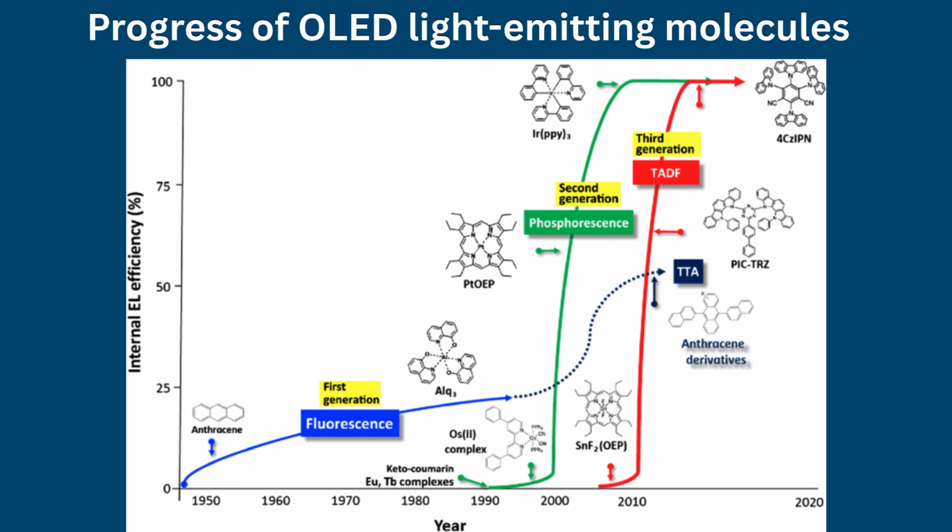In conclusion, OLED technology has undergone significant advancements, transitioning from low-efficiency fluorescent systems to highly efficient phosphorescent and TADF-based devices. Despite these developments, achieving stable, high-efficiency blue emission remains the principal challenge. Future progress will depend on the rational design of emissive materials, improved device architectures, and a deeper understanding of degradation mechanisms. The integration of advanced emitter systems such as MRTADF and hyperfluorescence, combined with optimized charge transport and encapsulation strategies, is expected to drive the next generation of high-performance OLEDs.